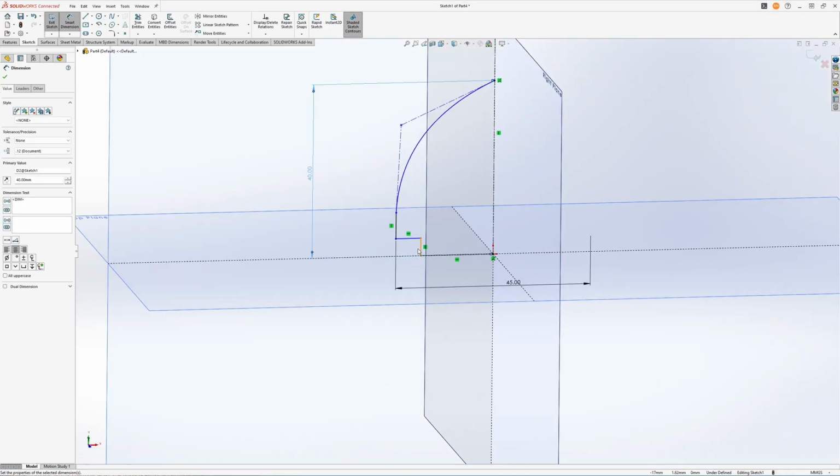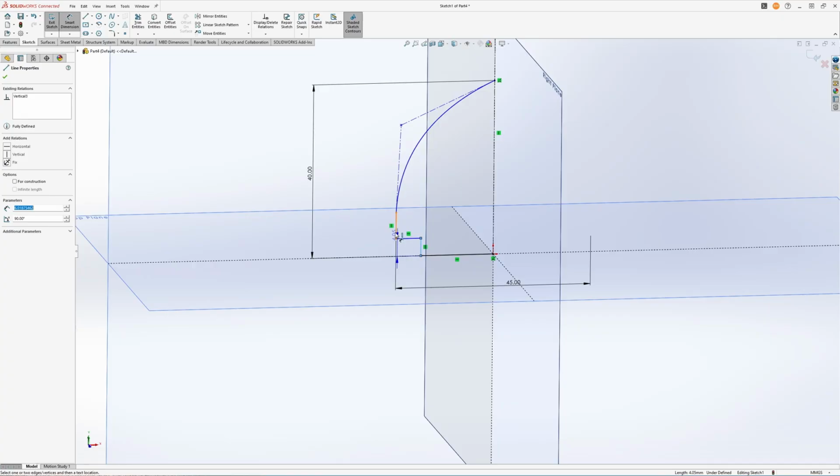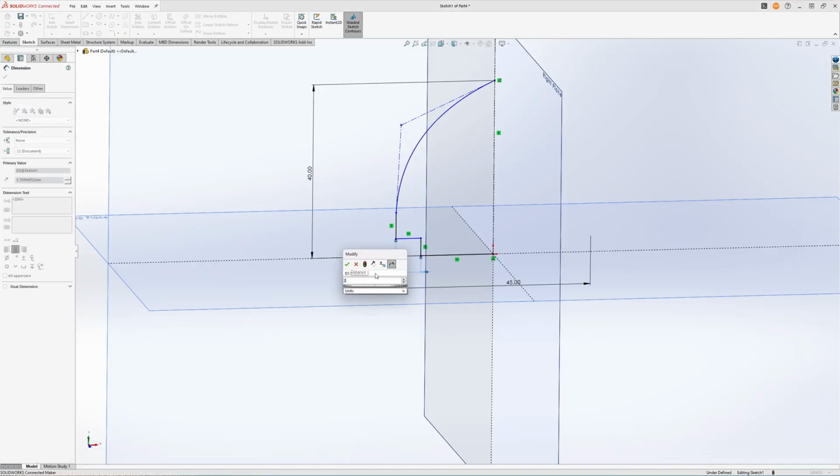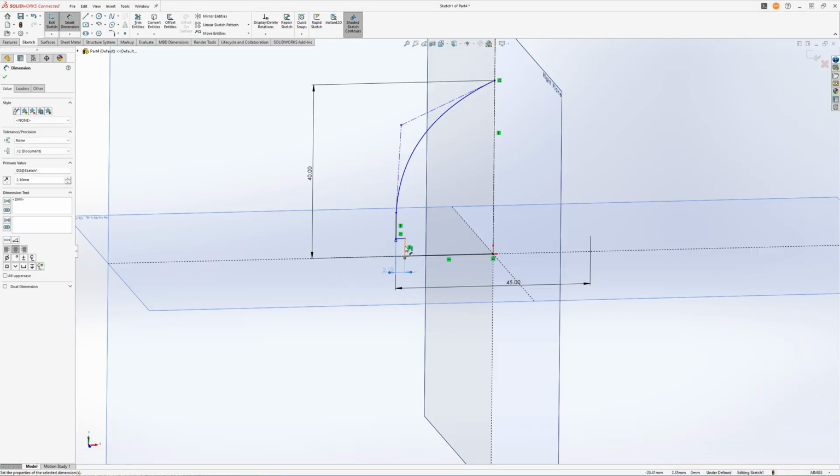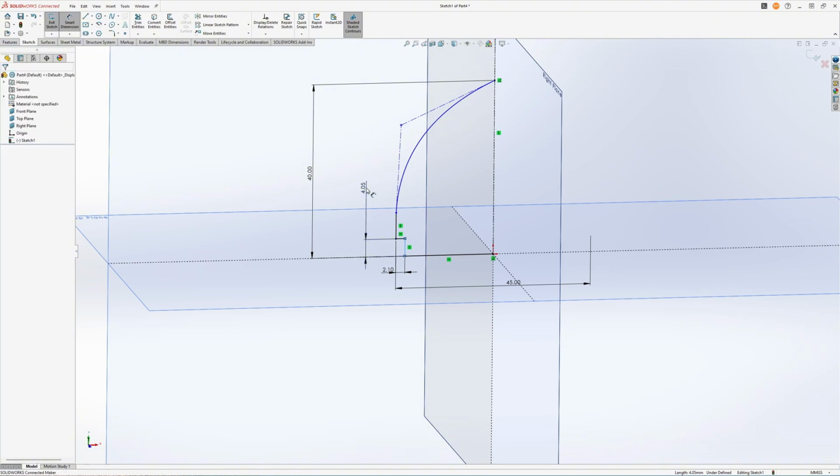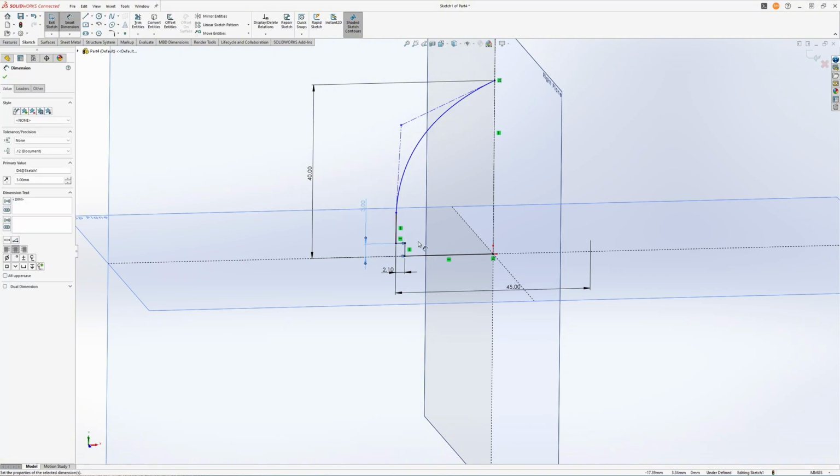And let's try to do an inner. We said the wall thickness was about 2, so we want at least 2.1 so that we have some clearance for the parts to fit through. And let's do some overlapping geometry of 3. So this will be however much material goes down into the other part. We'll see that later.